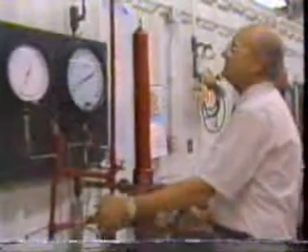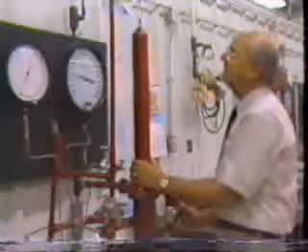Now I'm going to raise the casing pressure on the valve. See the pressure building up, 200, 300, 400, 500. Now I expect a calibration pressure of very close to 850 pounds, something like that. So I'm going to put a little bit of tubing back pressure on this valve.